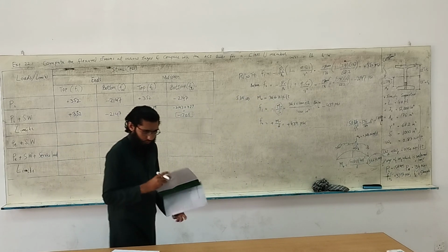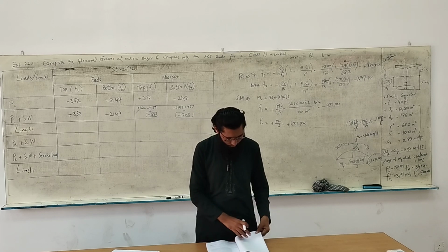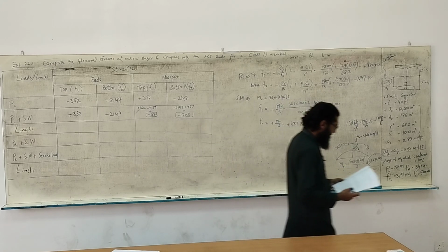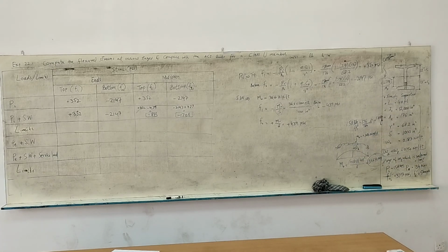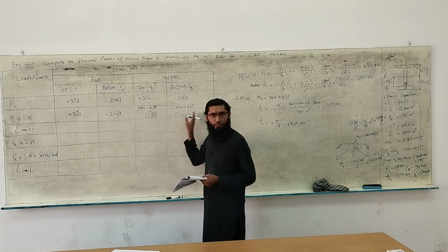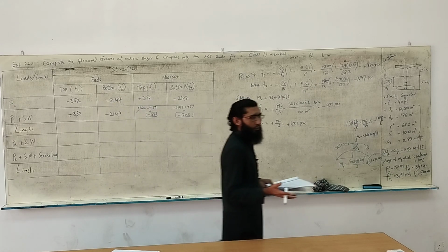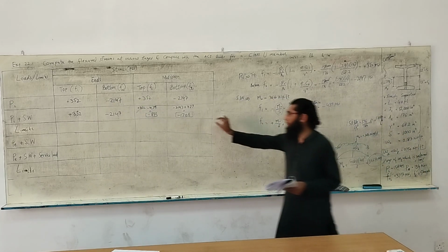Now let's come to table 22.1, I think. If you don't have it in printed form, you can just pull it from your mobile screen. So table 22.1 in the book, yes please. Yeah, all of it is in compression. One side is heavily compressed, the other is just a little bit in compression. So we don't have a neutral axis in this superimposed stage.